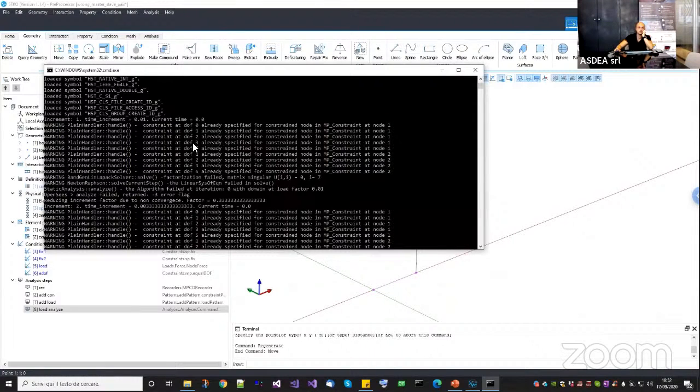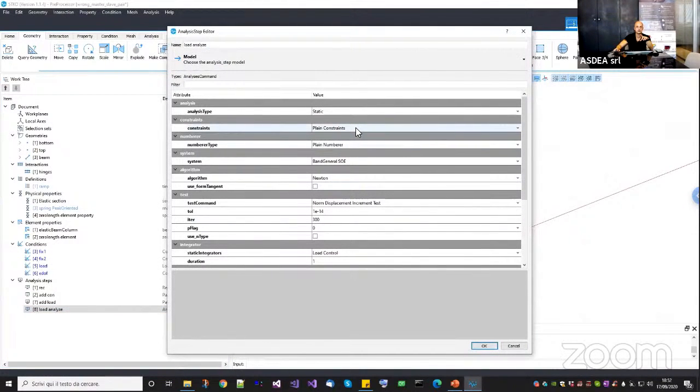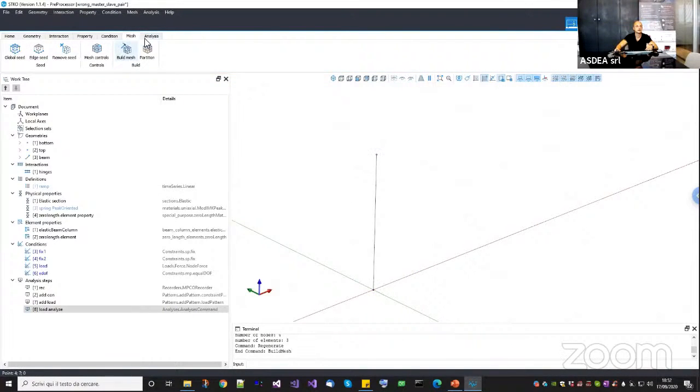Now, fortunately, if you use the plane constraint, it gives you this warning. So if you already understand how OpenSees works, you can easily realize that the error is due to the constraint handler. But actually, I want to show you that this is not a rule because if you choose the transformation, and I can make sure that the problem is the same, it will give you exactly the same error. Let me move it back to its position, and I remesh it.